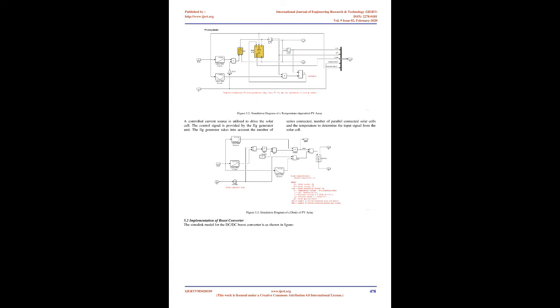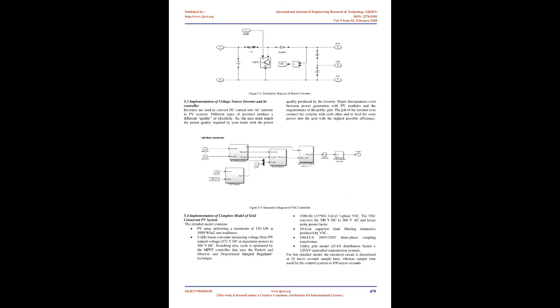3.1.2 Incremental conductance method. This method uses the PV array's incremental conductance, dI/dV, to compute the sign of dP/dV. When dI/dV is equal and opposite to the value of I/V, where dP/dV equals 0, the algorithm knows that the maximum power point is reached and thus it terminates and returns the corresponding value of operating voltage for MPP. This method tracks rapidly changing irradiation conditions more accurately than the P&O method. One complexity in this method is that it requires many sensors to operate and hence is economically less effective.